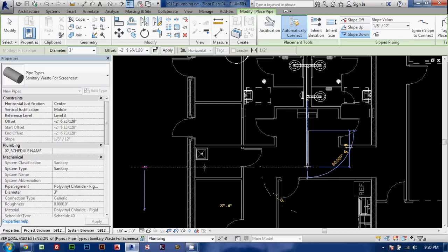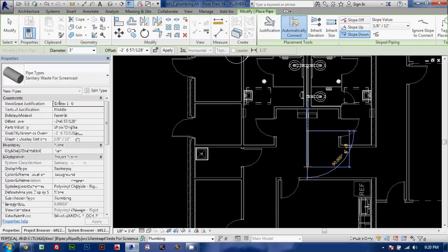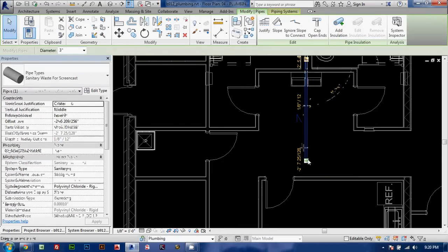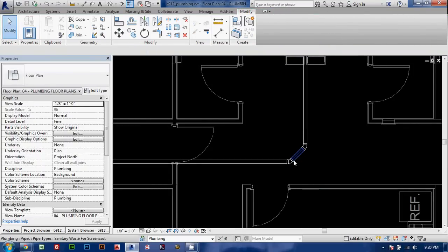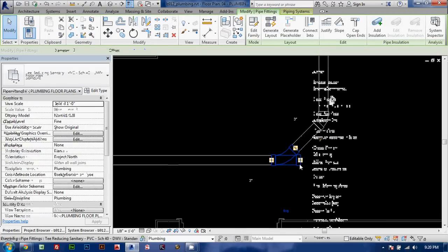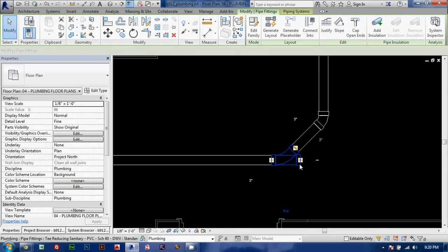Continue it out to, actually, I want to make sure I go ahead and have that 45 set in this so that we're, like I showed you at the beginning of this screencast, how that separation of pipe and drawing in a different direction can kind of mess with your invert a little bit, or your sloping. Then I'm going to go ahead and draw some pipe up this way.